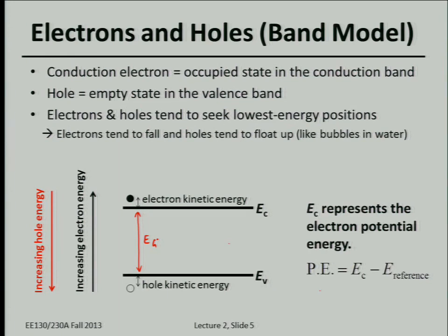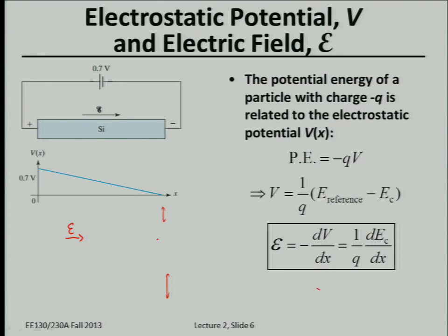So in any energy band diagram, you should have EC and EV always spaced evenly. If you see a slope in the conduction band edge, you should see the exact same slope in the valence band edge. The separation between the band edges should always equal the band gap energy of the semiconductor material.